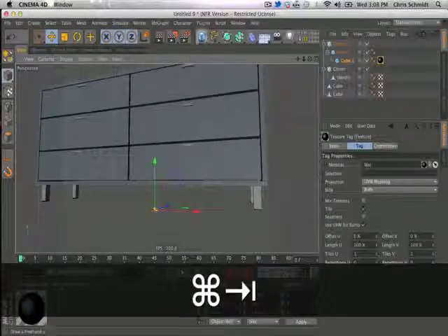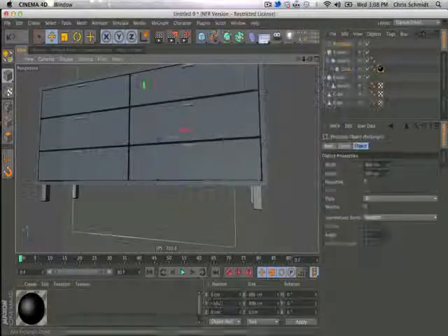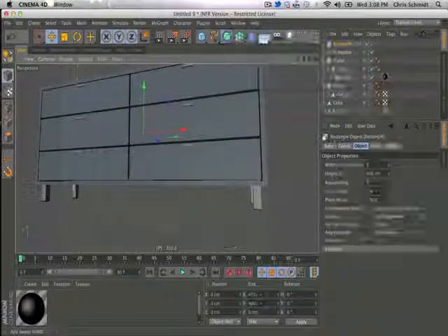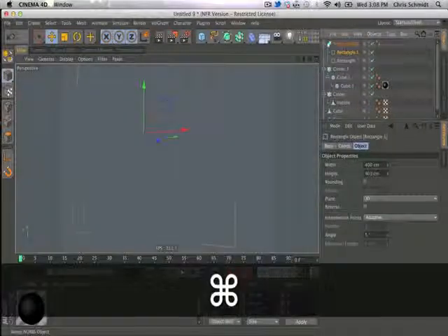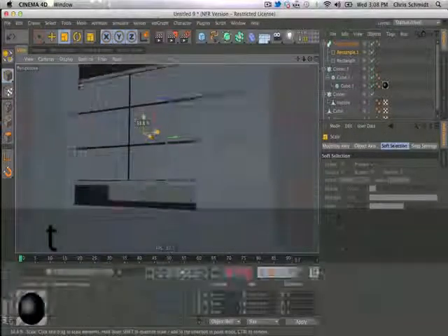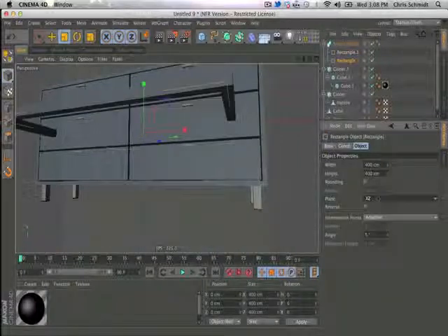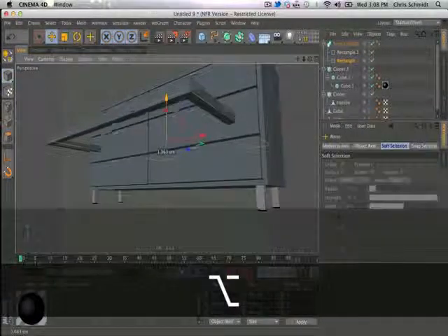which probably goes all the way around. Hard to tell at this angle, but the fastest way to make that would be to make a rectangle spline, and we'll make a sweep, and we need the rectangle spline and another rectangle spline, so I'll just copy that one. This top one has to be scaled way down, so we kind of start getting this little rectangle shape there. I'm going to change the orientation to be sideways,